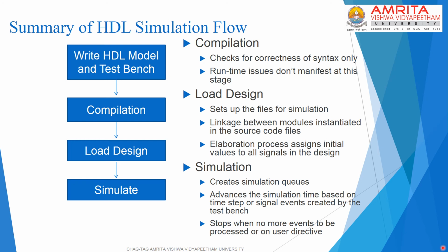So once the module and test bench are ready, these files are compiled. Compilation basically looks for the correctness of the syntax used in the code. Runtime issues like the range of values for a particular signal are not looked into during compilation.